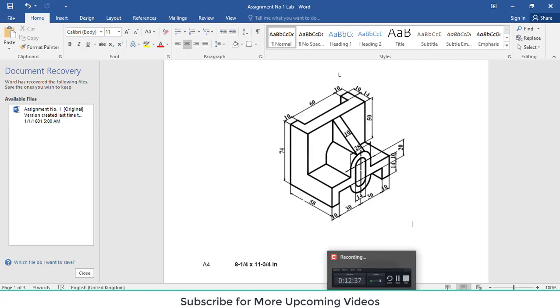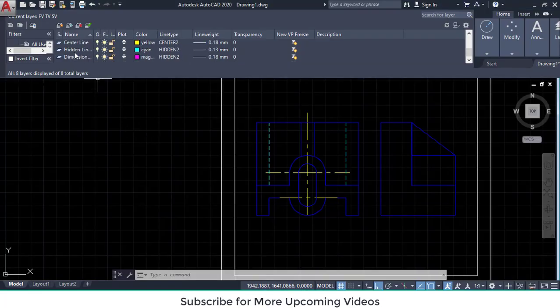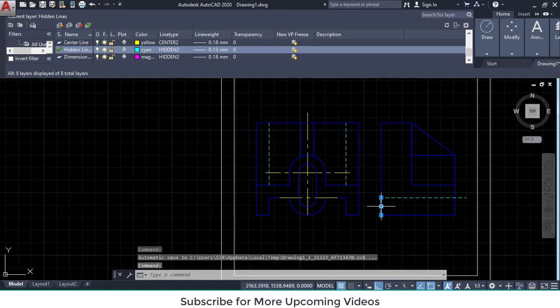So I draw this as a hidden line 14 millimeter from this side. As a hidden line, first I select hidden line. So line, 14 millimeter. Delete this portion, no need of this, and trim this extra portion.